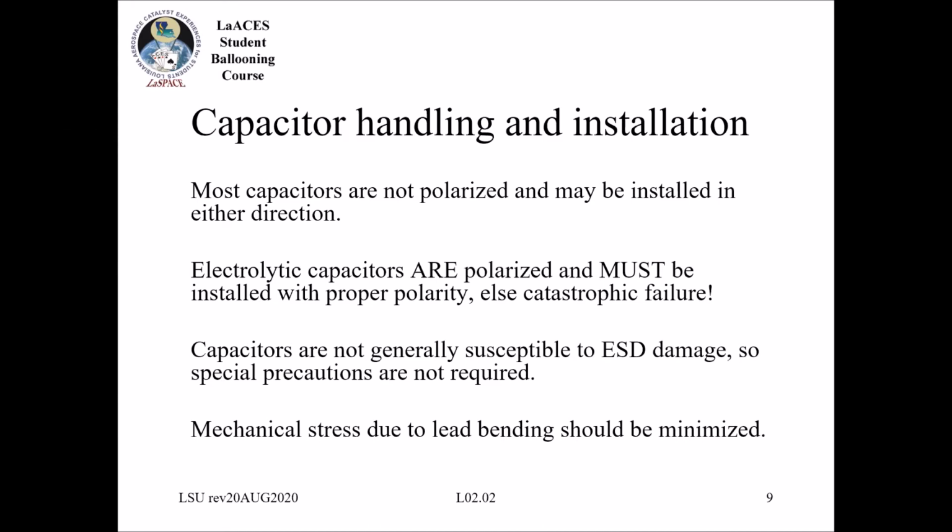This again is pointing out the electrolytic and the tantalums are polarized, and then it says here that they're not generally susceptible to ESD, and then again the same problem with the resistors with the mechanical stress from the leads. This is definitely true with the capacitors. I feel like they're even weaker than the resistors in many cases. So just be aware of all of that. Again, these things are normally cheap. They come in a lot. So when you order them, you'll have a package of them. Just switch it out.